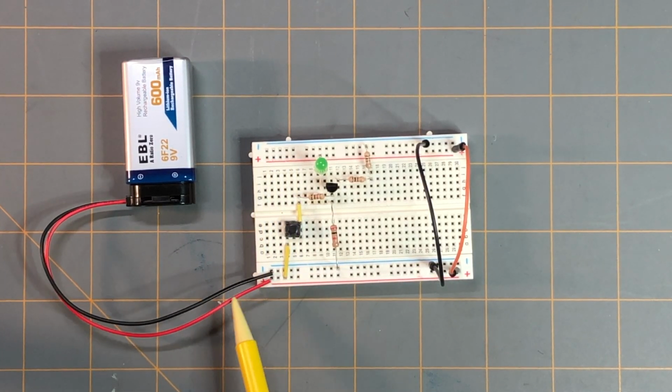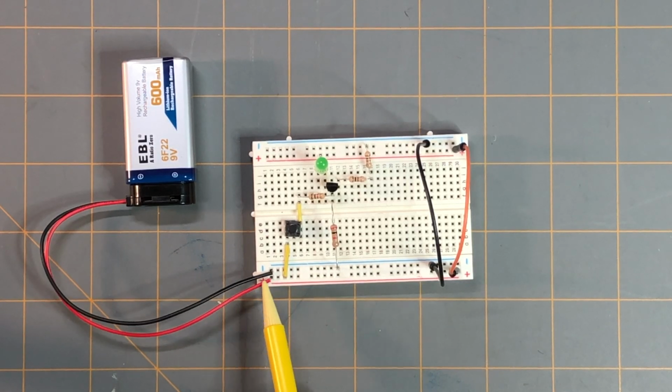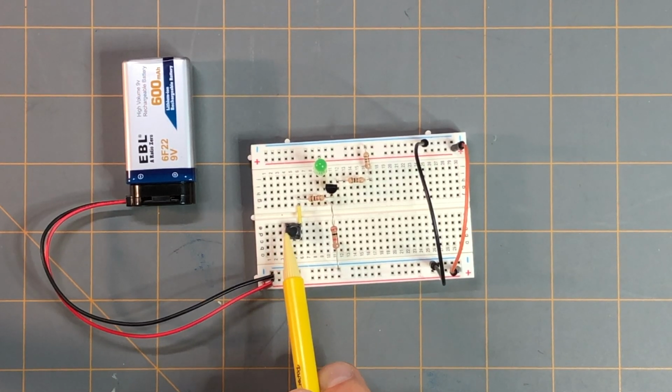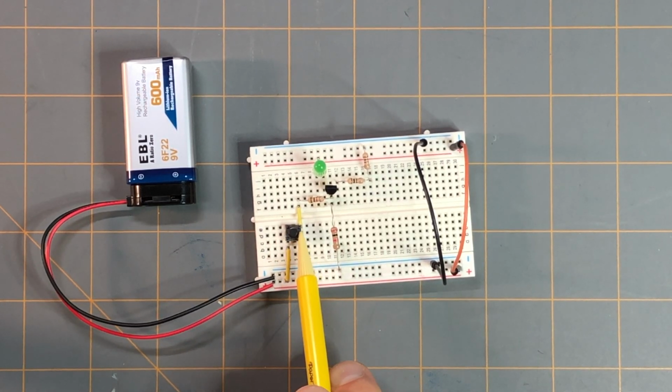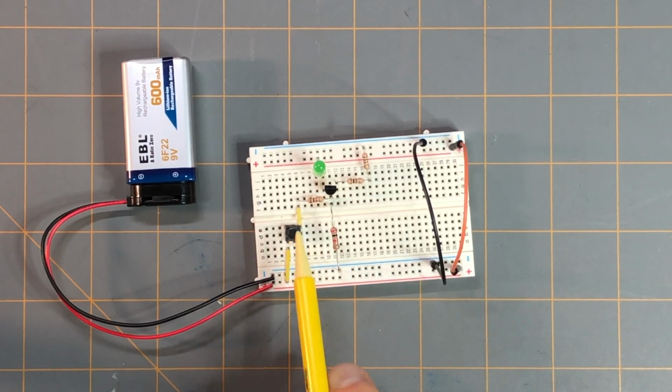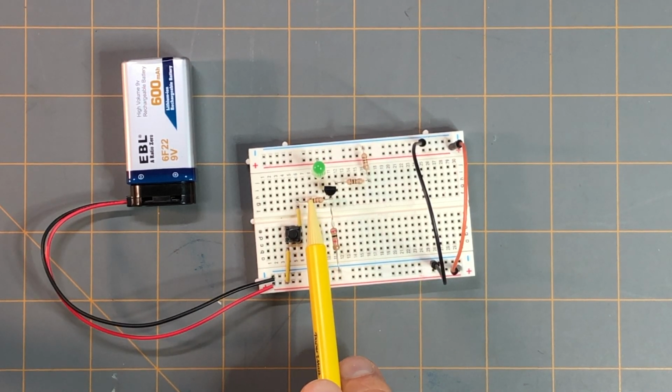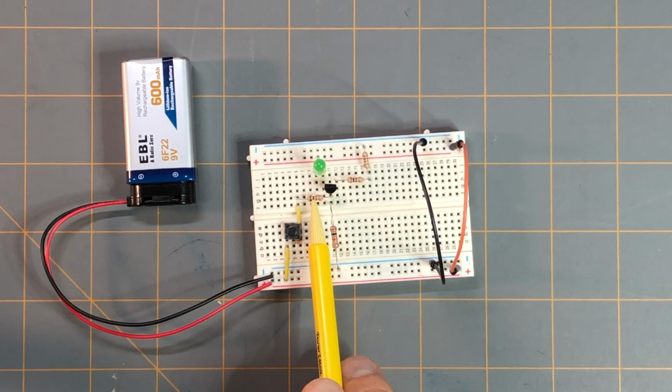And again, going back to that positive lead of the battery, it goes to the positive power rail, to this yellow jumper wire that goes to a lead on this push button switch, a normally open push button switch on this end. And then the other terminal on the other side of that push button switch is in line with this yellow jumper wire, which is in line to the lead of this resistor here. This is resistor R1 in the schematic. Again, you can find that schematic on the website. I'll leave the link to that down in the description below.